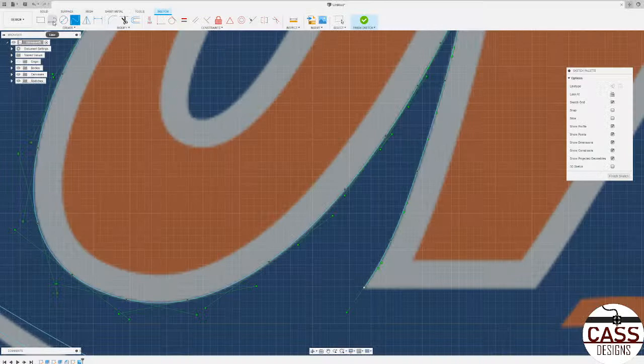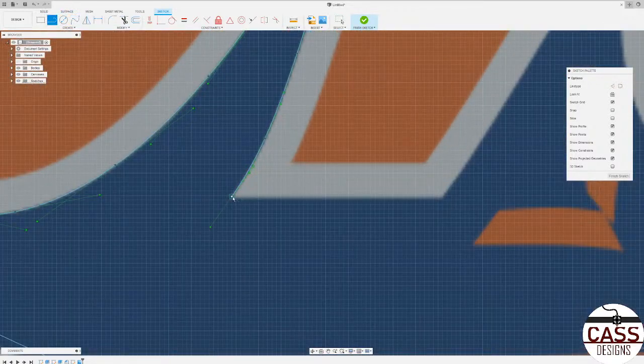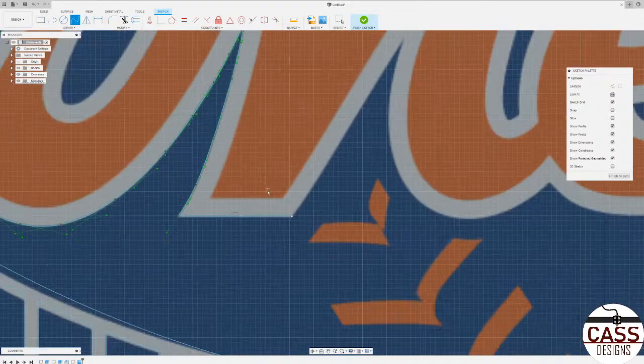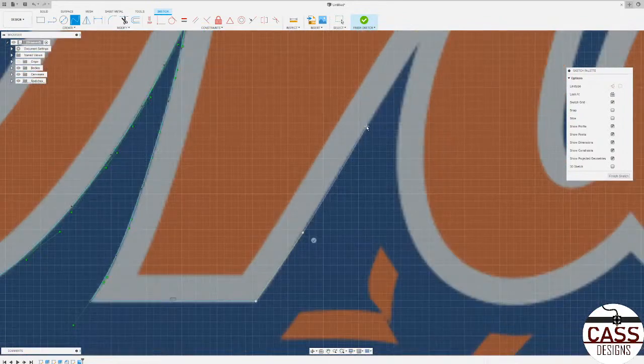Okay. So all I did was click fit point spline up here and trace around this to create these two splines, which I'll show again in a second. And now going back to line, you click this and trace a flat line to the edge over here. Finish that. Go back to the spline to outline this very slightly curved edge. Click OK. Now we're going to create a new spline at the end of this one to trace around this part of the M.